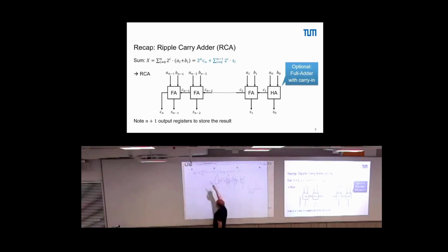Despite the fact that in 2's complement the most significant entry has a negative sign, the sum remains completely the same. That's the only difference if we go for 2's complement. Meaning this adder here also works for 2's complement numbers. So, if this works for 2's complement numbers, and we want to subtract one number from another, what do we need to do? Well, we do this conversion: invert, add 1, right?